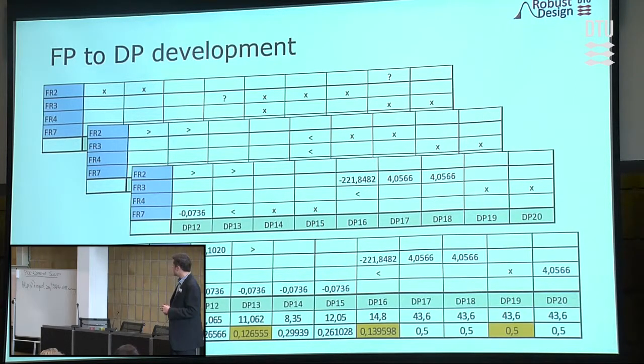And then, of course, when we start filling in the matrix more and more, we can start defining the nominal dimensions and the tolerance windows and stating where our tolerances we're unsure of due to unfilled out sensitivities. So we can leave placeholders as places where we're not quite yet certain of.